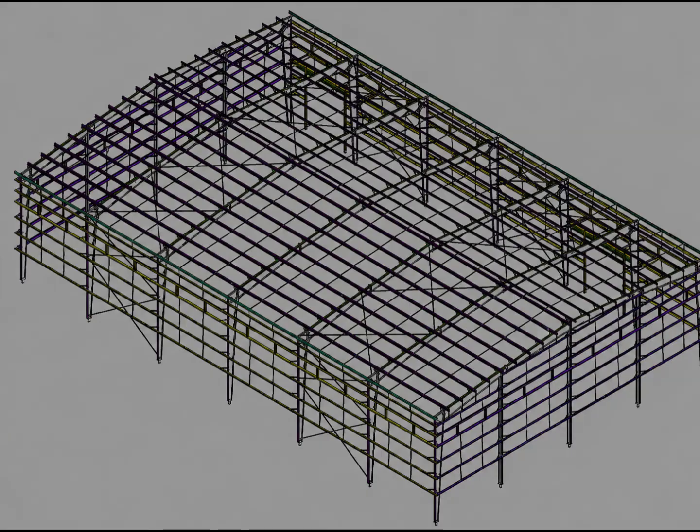For a structural draftsman or PEB detailer, this skill is extremely valuable. You may receive a project containing hundreds of framing members. The challenge is not simply drawing lines. The real challenge is understanding what every important line represents and where it belongs. If a small member is missed during modeling or detailing, it can create problems later during fabrication or erection coordination. Therefore, systematic member tracing is an important part of quality control.